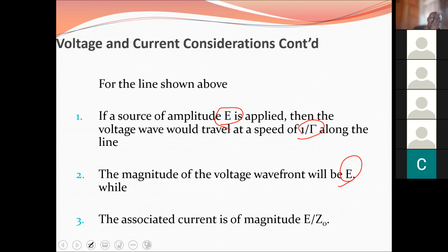So we'd have a voltage from the sending end, a voltage at the first admittance, then a voltage at the next, and then at the next, because we're having voltage drops due to Z. In a sense, what we are doing is charging those capacitances along the line, which is why in power systems we usually say that we energize the line or we charge the line, whichever floats your boat. All right?